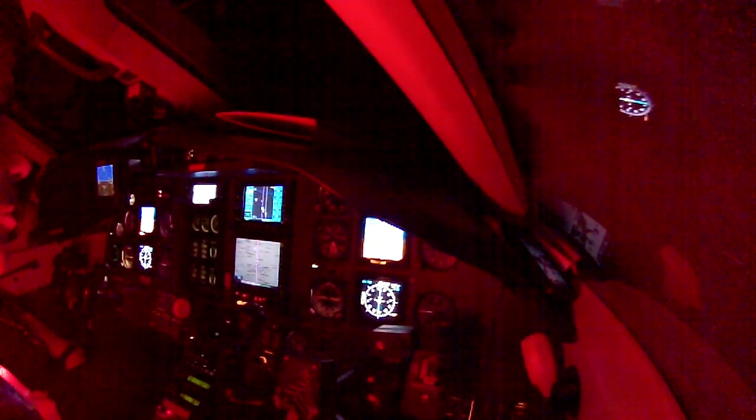So if you're looking at these two instruments, you can derive everything you want from here, other than altitude: attitude, heading, course selected, desired track, distance, speed, estimated time to checkpoint, what AHRS you're using, what mode is selected on the flight director, and if autopilot and yaw damp are on. Everything is on these two electronic boxes.